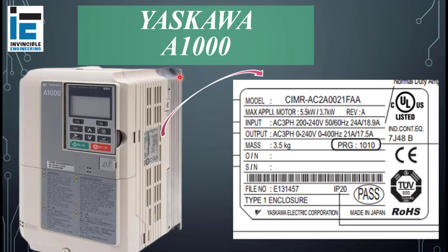Here we will use the Yaskawa 8000 series. This is the picture of the 8000 model. On the right side of the VFD is a description label. On this label we can see the input of the VFD, which is AC 3-phase 200 to 240 volt, 50 or 60 Hz and 24 ampere.